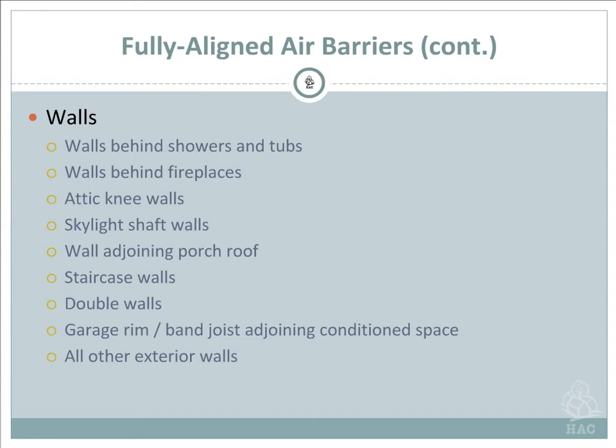But what should have happened before the contractor comes in to install that tub, you should have already sealed the base plate, the bottom plate. You should have sealed your corners. All that stuff should have been done, and the insulation in that corner should at least have been installed, if nowhere else in the house. Again, behind walls, behind fireplaces.